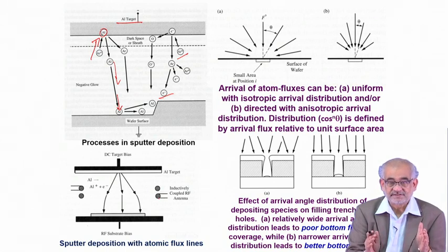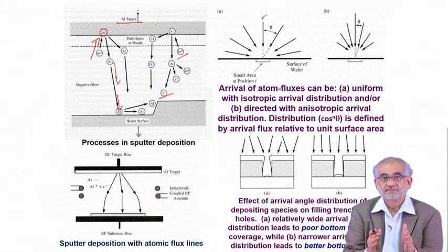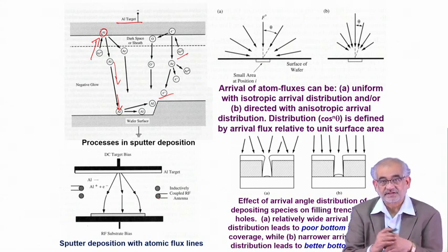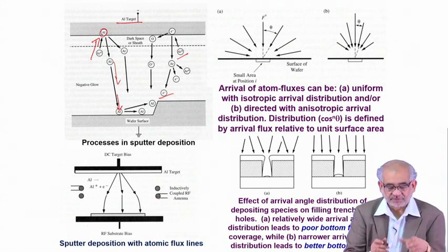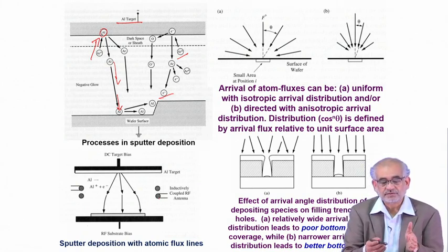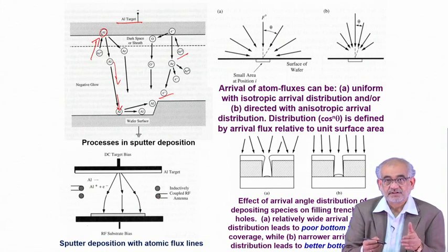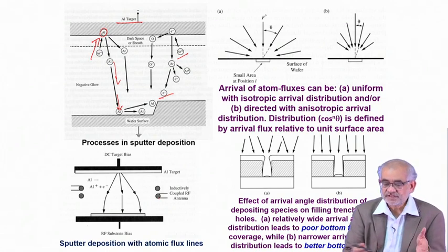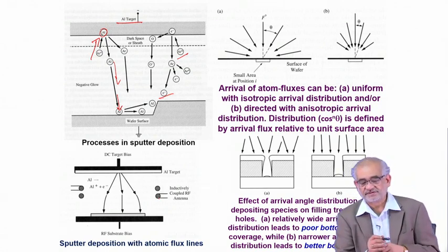One possibility is that you confine the plasma by applying a high flux, high power magnet, typically a magnetron, and then you call it magnetron sputtering. Similarly, the frequency of the sputtering can be changed from a normal electrical power supply to an RF coupled power supply, and accordingly there could be certain differences.